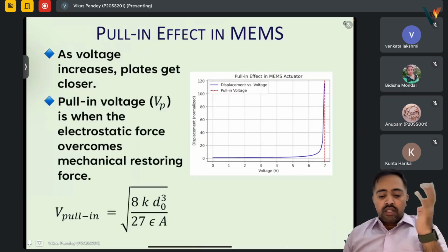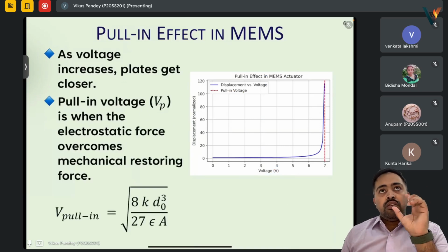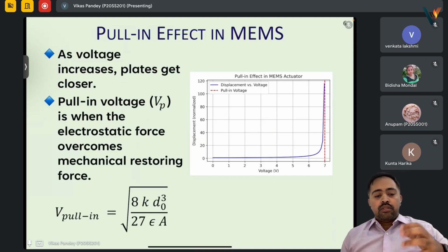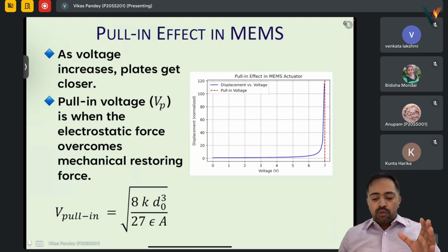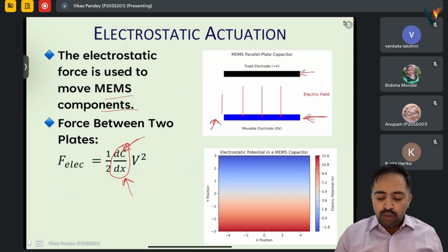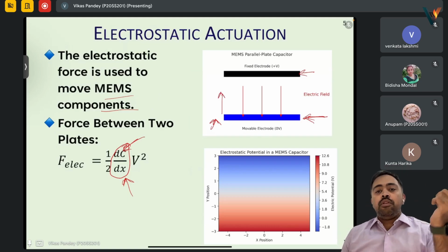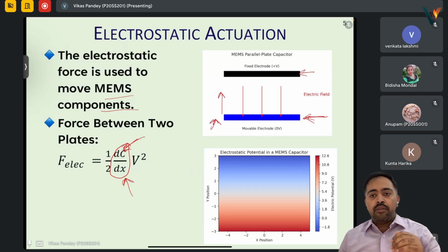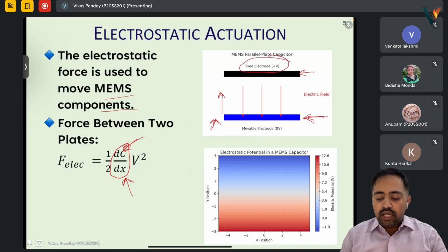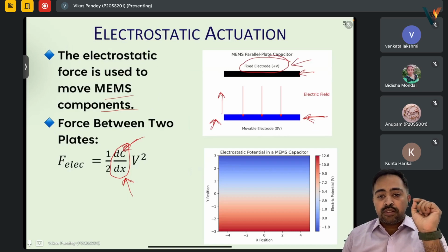First, the voltage and displacement will have some relation. Let's suppose we want to pull this moving electrode towards us, so we will apply some voltage. When we want to push it away, or have it at equilibrium, a voltage has to be applied. So the control is in terms of voltage.